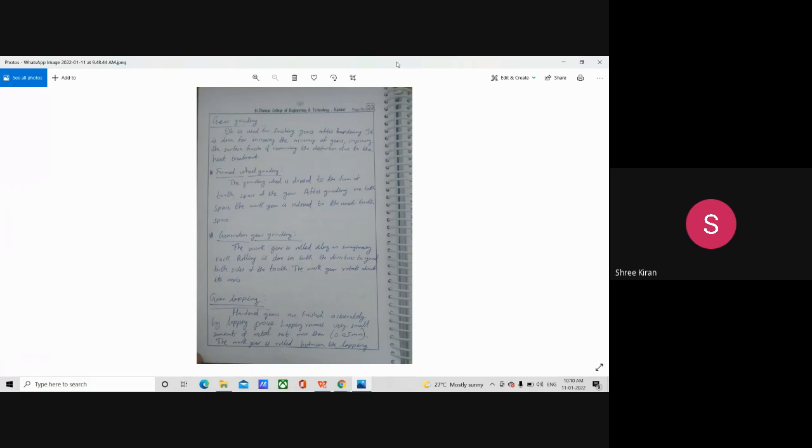Will the material removal rate be high, normal, or minimum? We are told that we have to achieve accuracy, improve the surface finish, and remove the distortion due to the heat treatment. All this we are doing using the gear grinding process. Okay, and we have listed down the various types of gear grinding processes also. My question is, what is the purpose or what is the requirement? Whether in the case of the gear grinding process, an enormous amount of metal gets removed or a comparatively minimum amount of metal gets removed. That's one question.